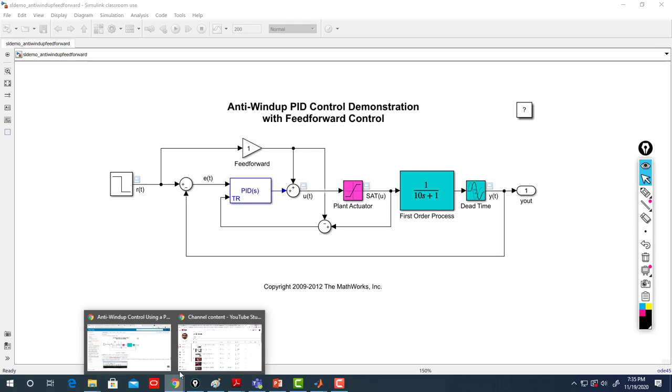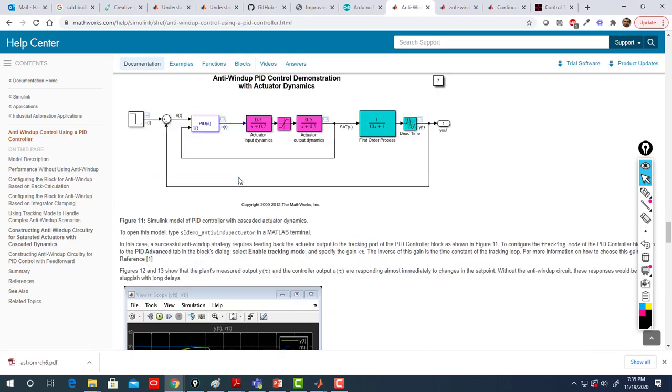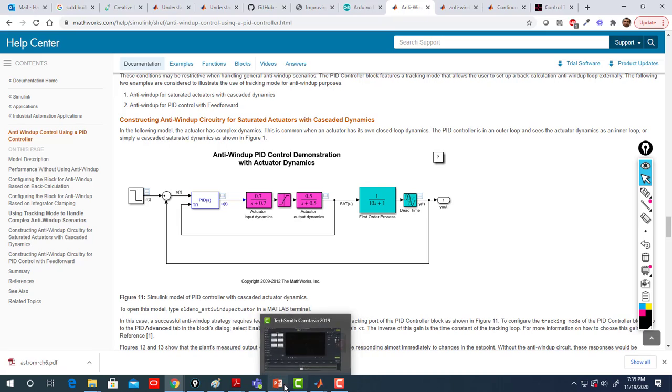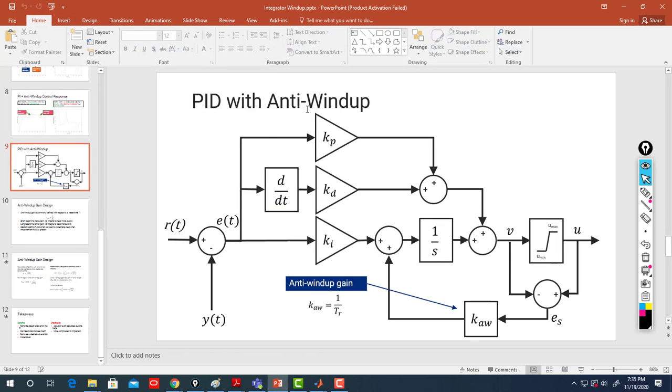If you don't want to go into this and even the below one, you can stick to applying directly what we said here. Then you need to build your own PID, and it's easy to build your own PID. You put the proportional, the integral, the derivative, but pay attention to the derivative. You need to add a filter on it, or sometimes, instead of using the error, you could feed the output directly and derive the output. All right, so you could build the system yourself and make your life easy.